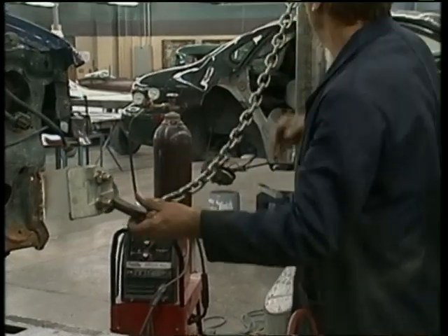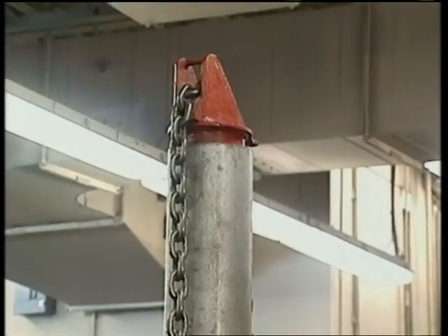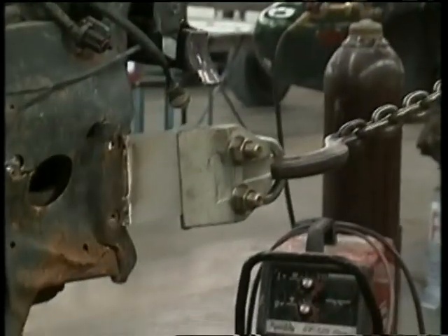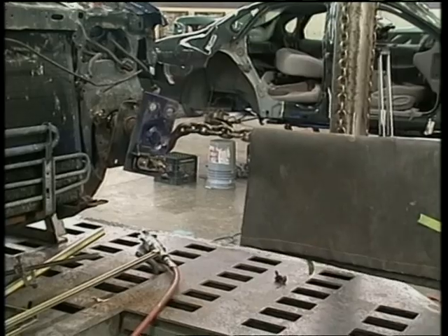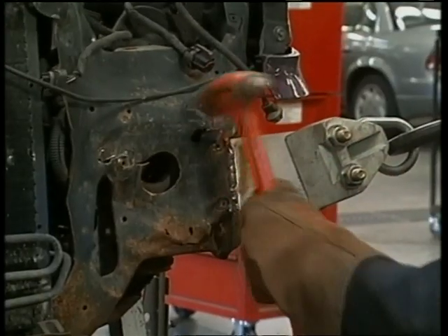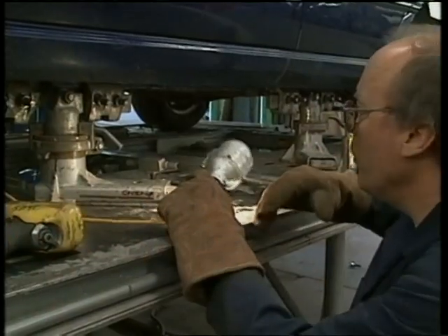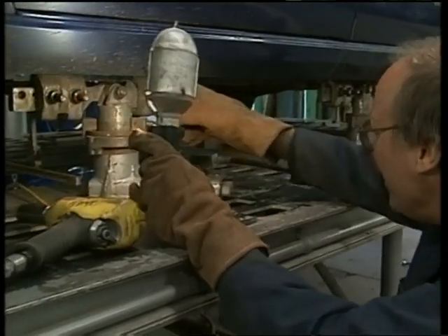The other end of the chain is attached to the hydraulic puller. Take all of the slack out of the chain before applying pressure. Corrections and fine-tuning will be needed as you progress with the pull. Remember to pull, measure, pull, and measure. Carefully monitor the pulling process and check your anchoring locations.